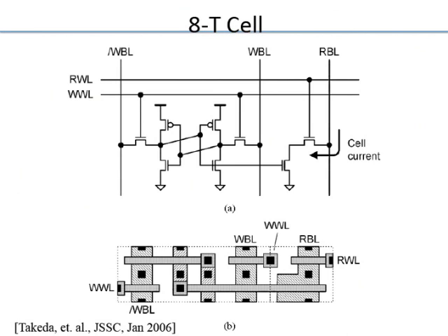If I had 2 different decoders, I could do write and read at the same time, as long as they are in 2 different rows. Okay, so I can have a dual ported memory with this structure.